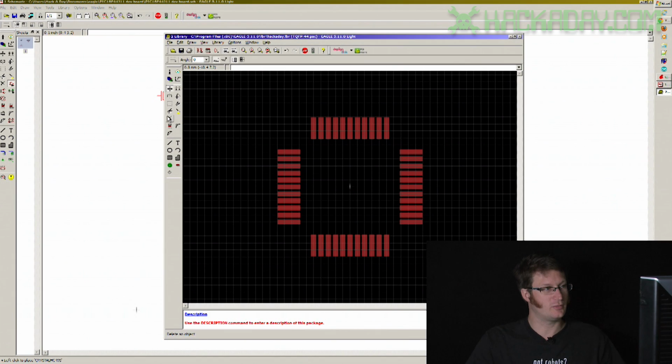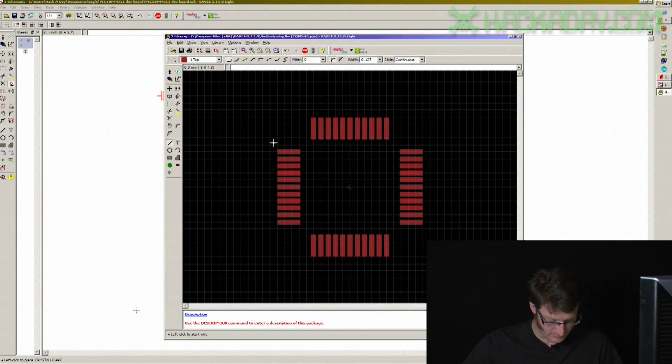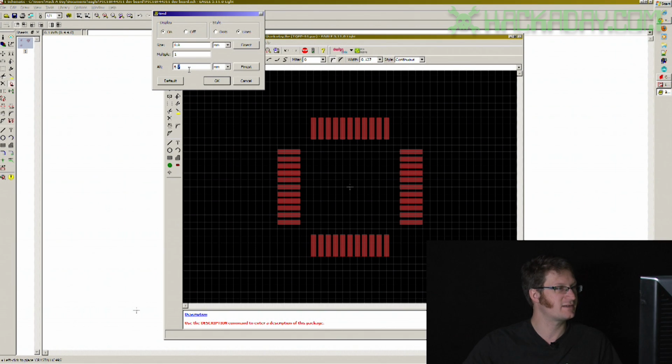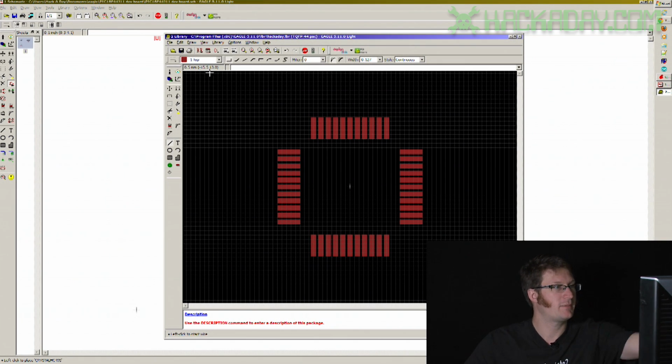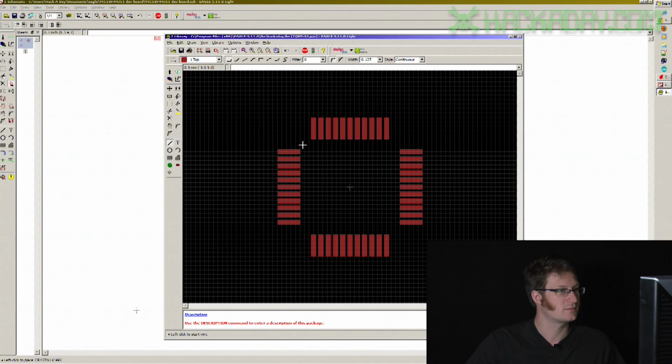Now it's time to indicate where the part might be sticking out of. In my case, D1 and E1 on the part sheet are 10 millimeters. So I'm going to change this to 1 millimeter. Actually, we'll change it to 0.5. And by looking right up here, I can see where in the grid I'm located currently. So I'm going to go to -0.5. It actually looks like my package doesn't stick out very far.